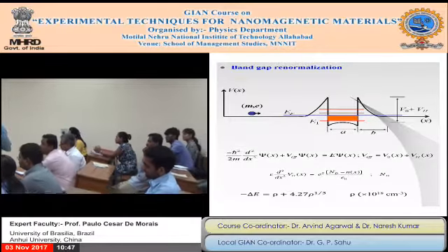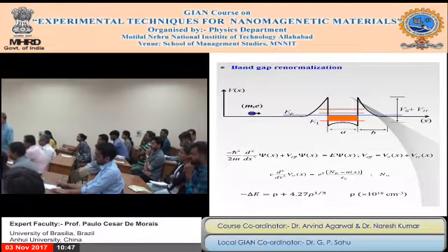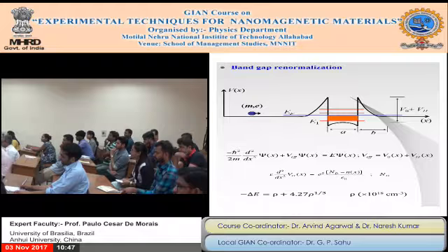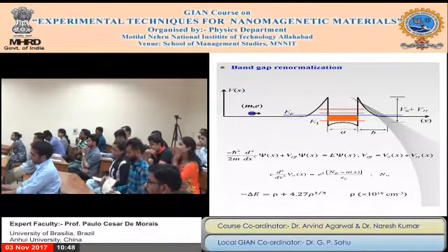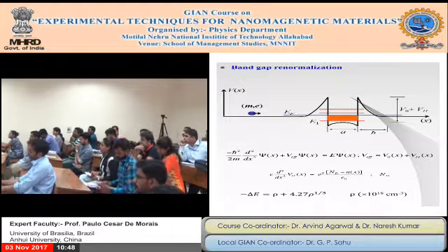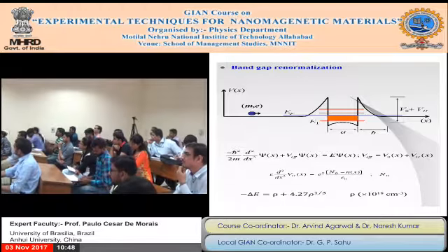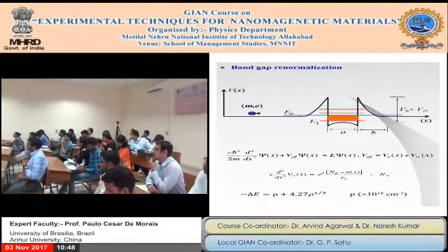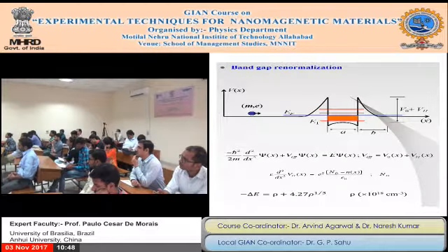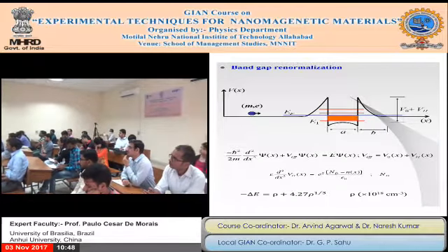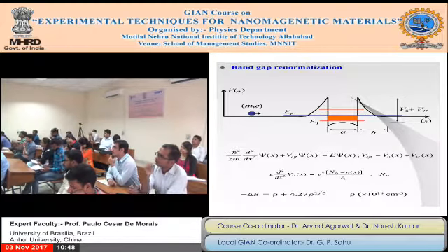But this bending here also shifts the energy levels. Besides this, when you accumulate charge in the same point in a semiconductor, it also shrinks the gap. It's called renormalization. That's the word. Because of the band bending and the band gap renormalization, the energy levels just move around.